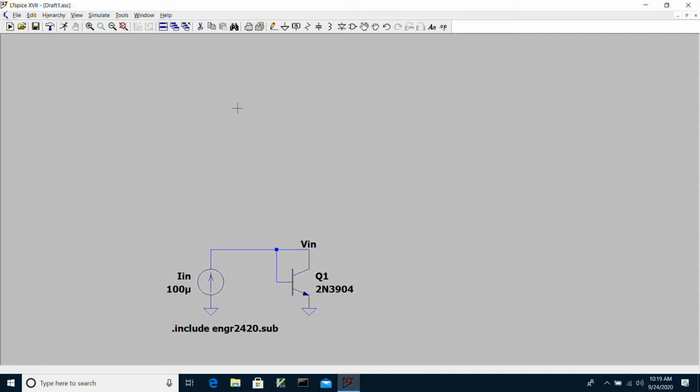And one of the things that Spice has built into it is some amount of numerical slop that's allowed in the satisfaction of Kirchhoff's current law at each node as it's trying to find the value of DC voltages in the circuit that will be consistent with the device's IV characteristics and Kirchhoff's laws.